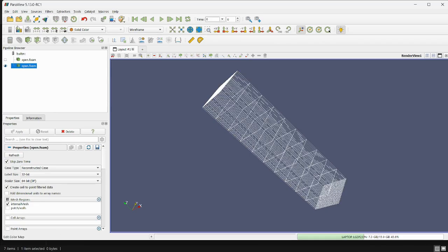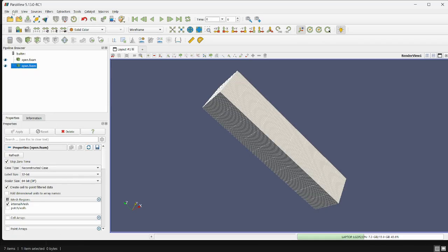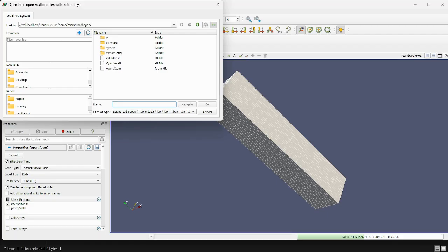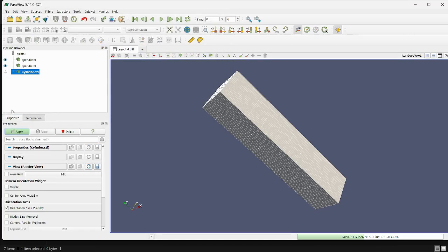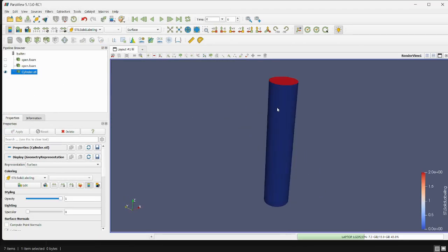So this is the block mesh, but you want to pick a point that's ideally towards the center. So we're probably going to pick a point along the center axis, which would be the z-axis, really. And our cylinder is 0.2 meters tall, so let's pick in the middle, 0.1 meters.